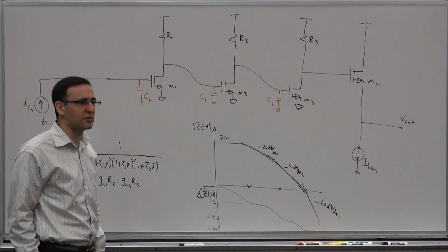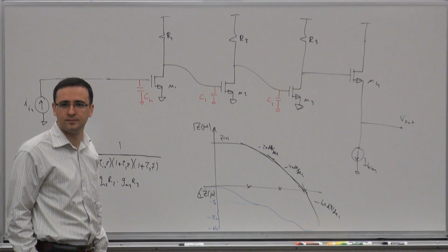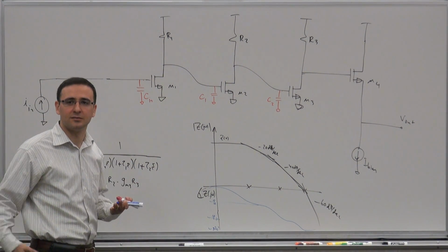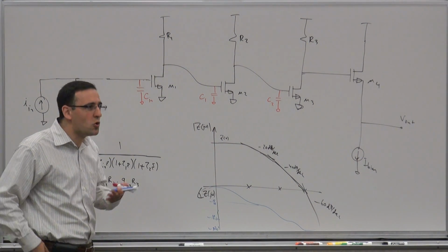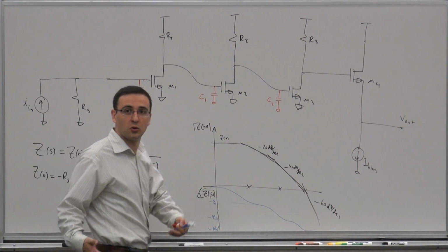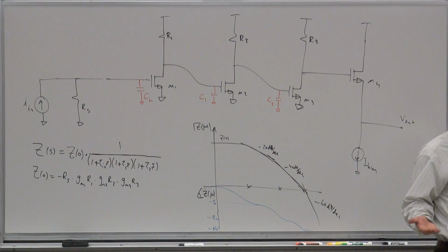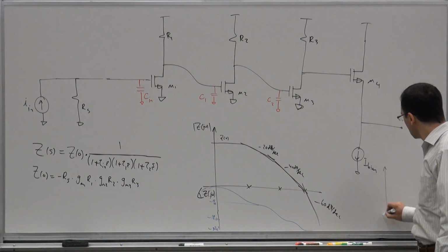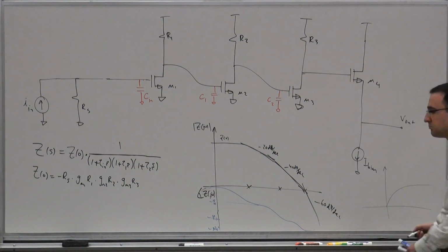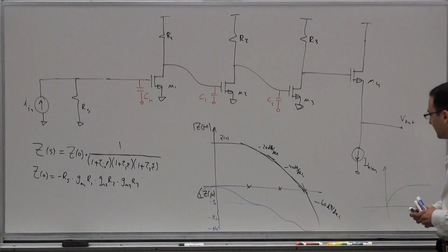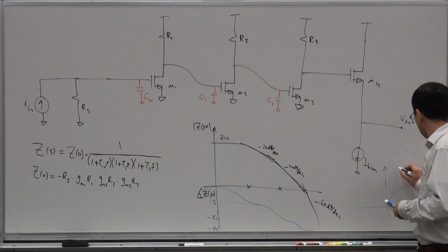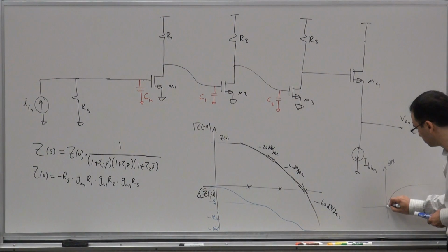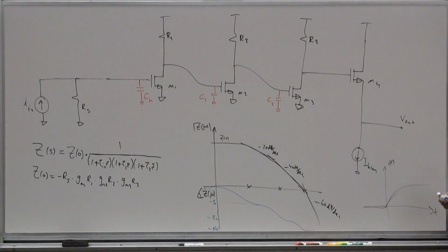How do you think the time domain response of this thing looks like? What would you say the time domain looks like? I mean, qualitatively. No ringing. There's no peaking here, no ringing, there's no complex poles. So it's just some sort of a combination of some exponentials, essentially. So the step response would look like that. Qualitatively. Nothing magical there.